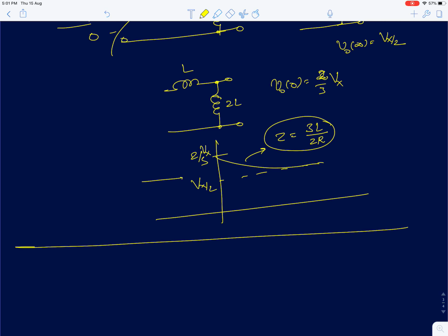So again, I'm not explaining this here. It's a leading phase system. There is a 0 in the circuit. So when you look at this time domain response, you should automatically connect that a response like this would imply there is a 0 and a pole in the system. And you should also infer from this graph that the 0 is less than the pole. You first encounter the 0 and then the pole.